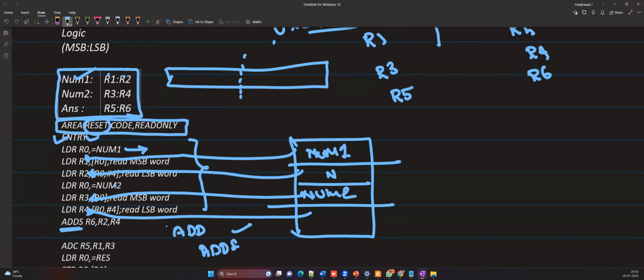So what is ADC? That is add with carry, right? I mean, that is not add with comparison, that is a comparison operation. We had seen various conditional operations, correct? ADDCC means carry flag clear, ADDCS means carry flag set. ADDC is not there, ADDCS is there, ADDCC is there. ADDMI, ADDPL are the conditional execution flags, correct?